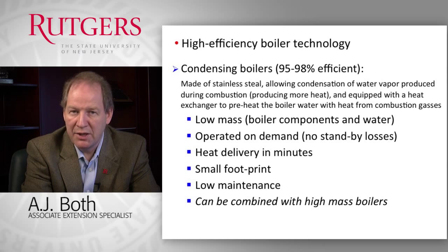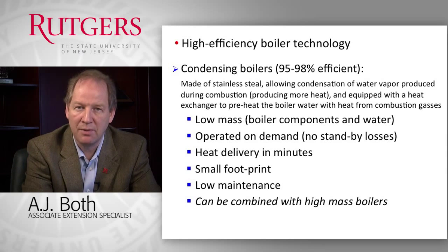They typically have a lot less maintenance than larger boiler systems, and they can be used in retrofit installations where you still have your larger boiler system, but you use these condensing boilers sort of as a first stage or a backup system or a boosting system, and then as a result you're able to still benefit from the increased efficiency that these condensing boilers provide. So I think this is something that you should look into if you're considering either upgrading or installing a new boiler system.